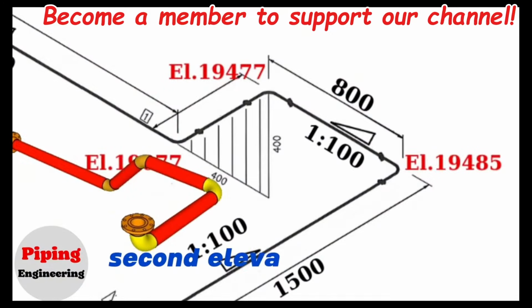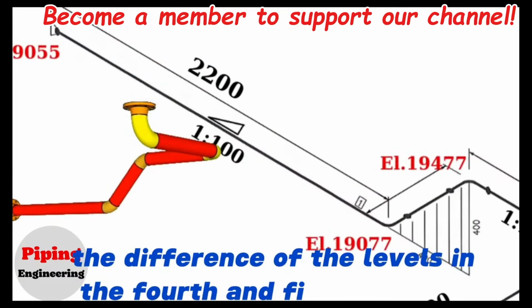Let's calculate the slope ratio now. In this pipe isometric drawing, the slope at a horizontal distance of 800 is expressed as a ratio of 1 to 100. 1 to 100 ratio equals x to 800 ratio. Here x equals 800 divided by 100. Continue the calculation and we find x equals 8 mm. With this method we can calculate the difference of the levels in the fourth and fifth turns. Fourth elevation 19,077 mm minus fifth elevation 19,055 mm equals 22 mm.